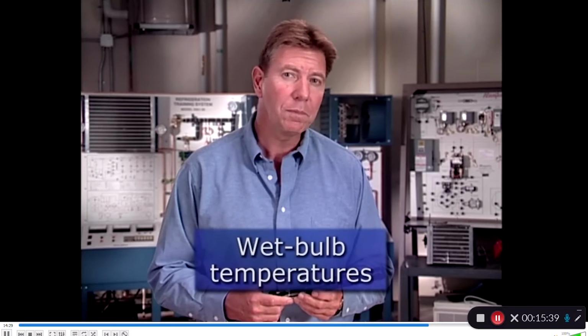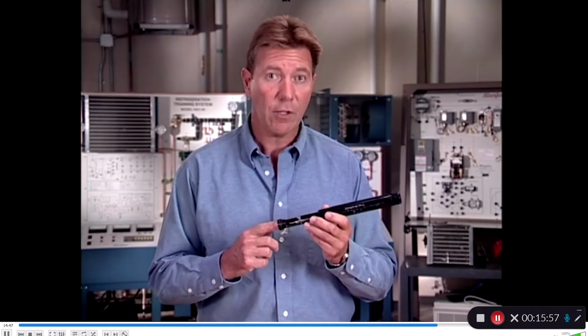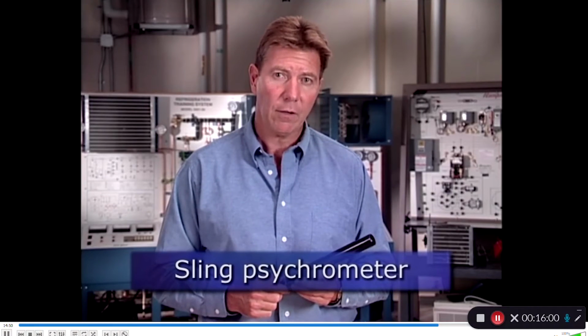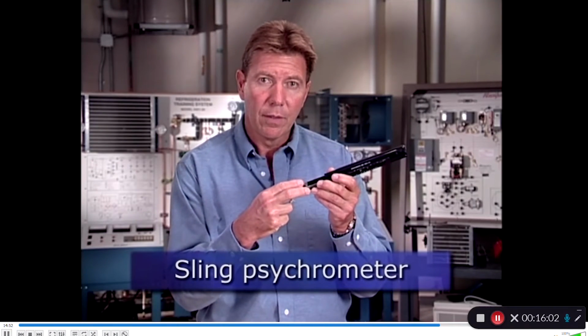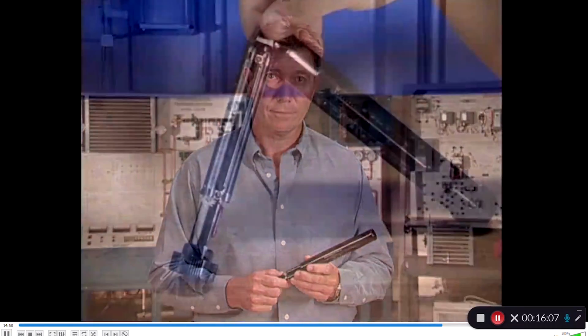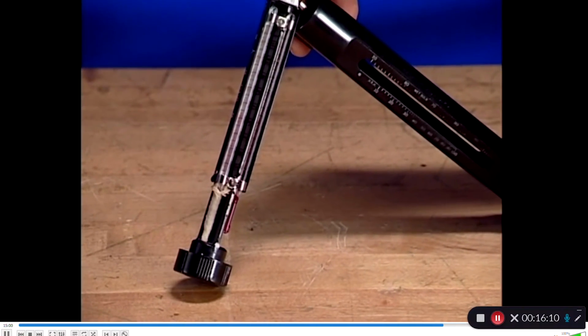The moisture content of air can be measured by using a combination of dry bulb and wet bulb temperatures. Dry bulb temperature is in the sensible heat level of air and is taken with an ordinary thermometer. Wet bulb temperature takes into account the moisture content of the air. To measure the wet bulb and dry bulb temperatures, we often use a sling psychrometer. The sling psychrometer is made up of 2 thermometers. One of the thermometers is kept dry and takes the temperature reading of the air. The other thermometer is surrounded by a wet wick.